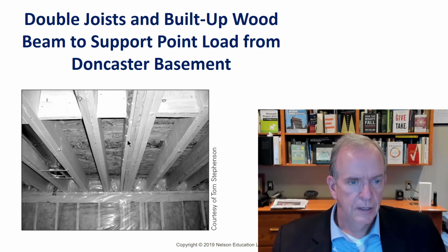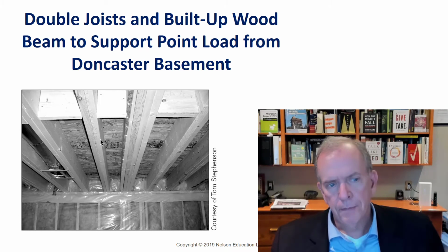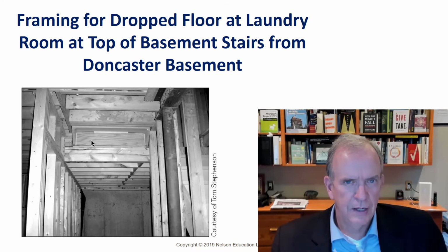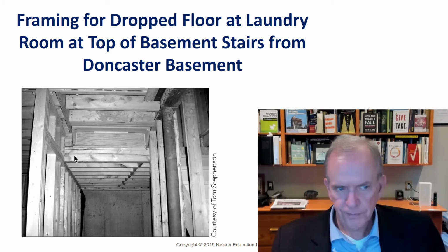We've already kind of looked at this. This is where that solid bearing goes. You can also see that the joists are doubled here. And I think I mentioned that in lecture 3A or 3B. That was because they're a little bit longer spans. So to keep with 2x8s, they doubled them. That wouldn't be part of part 9. They would have had that engineered under part 3, because they don't have doubling up of joists and stuff like that in part 9. So it would have been drawn by an engineer and they would have had their stamp on the drawings.